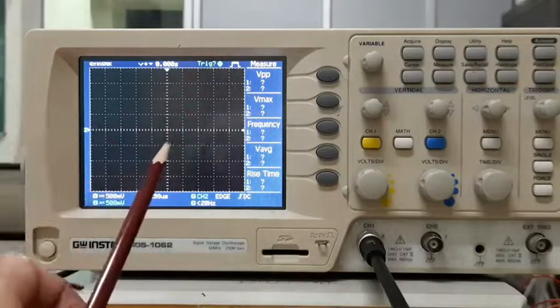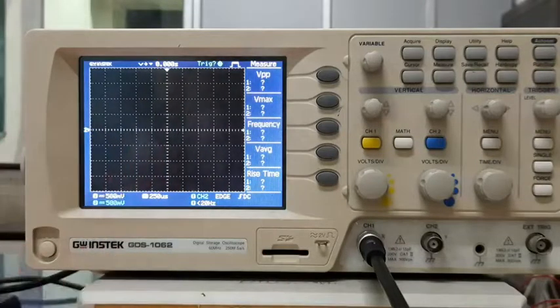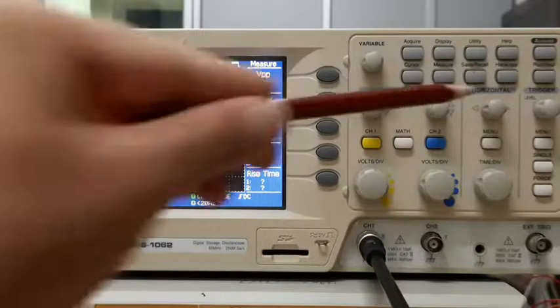But on the horizontal, since both the signals are measured with the same time reference, we only have one knob. So the time scale is the same for both the signals. Okay, so that's fine. And you are still not seeing the signal. That's because there is something else which needs to be set in these oscilloscopes, and that is called the trigger,